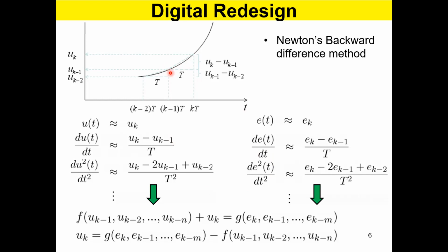So therefore, there is a time between samples where you don't know how the signal has changed, right? But you do the correction at the end of the sampling interval, looking at the overall or average rate of change. So these are all averages, right? Not the actual absolute rate of change.